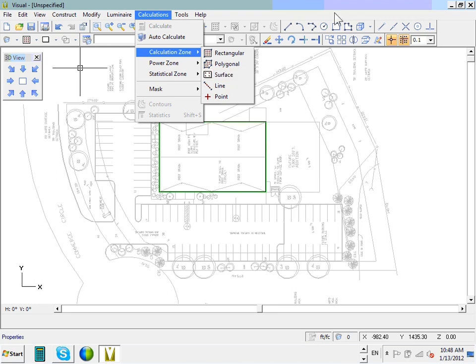So you can use either rectangular or polygonal. Polygonal. Yeah, exactly like he said. So that's the one I'm going to be using. And everybody knows why, because it's not a rectangular shape. I'm going to redraw around the whole parking lot. I'm going to start from this corner and track the whole parking lot all the way. I want to remind you, this is future, so I'm not going to go there. I'm going to go here, here, here, track it all the way up, cut here, cut here, cut here, all the way to there. And why didn't I use surface? Because there is no surface here. I want to use just redraw. Very easy. Cool? Everybody knows where we are?